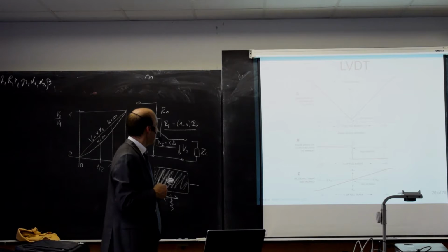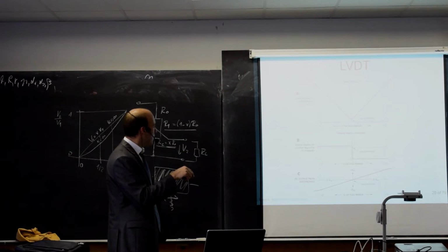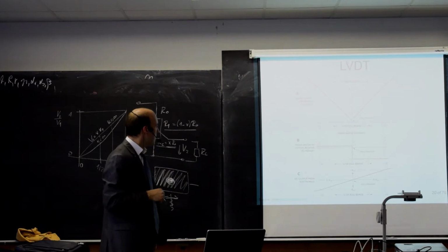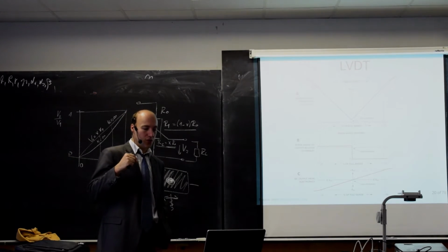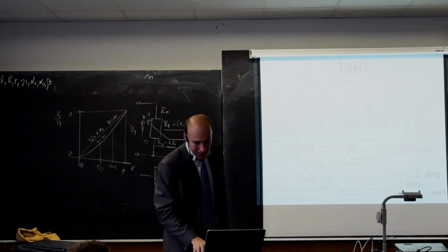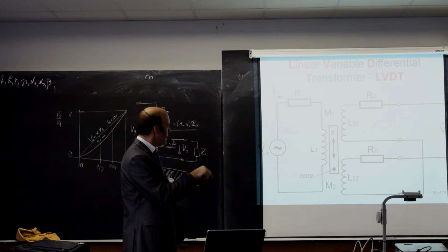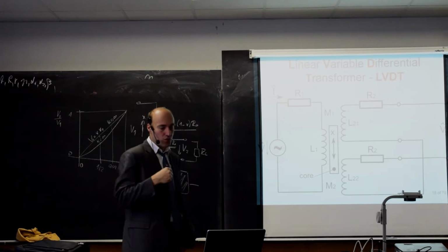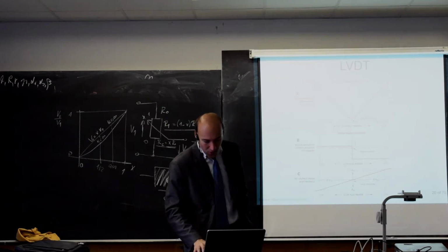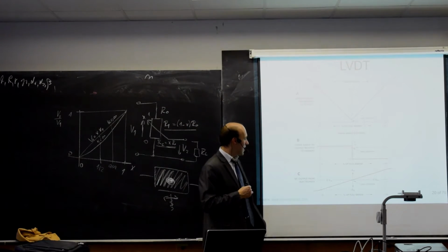This is another example of a steady state characteristic. So for the null position, we have non-zero voltage. This is one linear section, another linear section. If you watch also for the phase angle between the voltages at the secondary winding, so between this voltage and between this voltage, the phase shift will also change, and we can detect that with some kind of circuit.